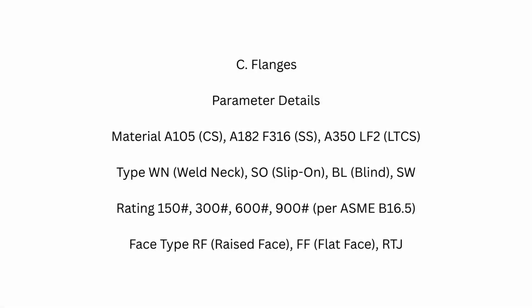Flanges, parameter details. Material: A105 CS, A182 SS, A350 LF2 LTCS. Type: WN weld neck, SO slip-on, BL blind. Rating: 150, 300, 600, 900 per ASME B16.5. Face type: RF raised face, FF flat face, RTJ.